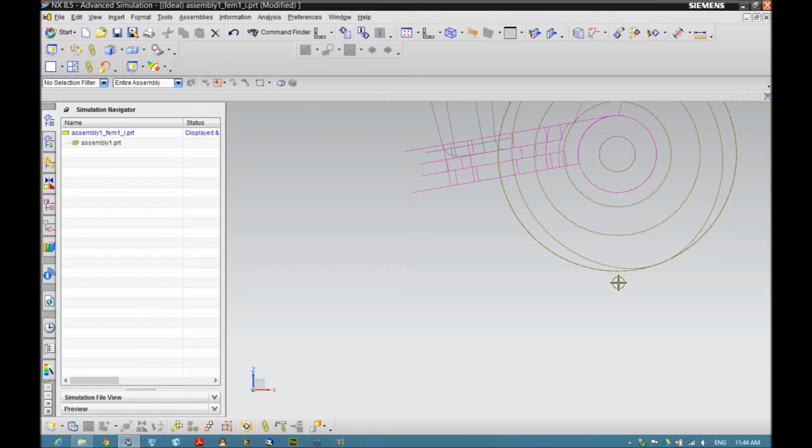So when you do a contact, you know that your force will be applied to this bottom, which is the contact point of this wheel to the ground. So let's say you have a node on the left side and the right side, so when you do a contact, actually the ground will contact the lowest part of this node, but this is off from the actual situation in real life.